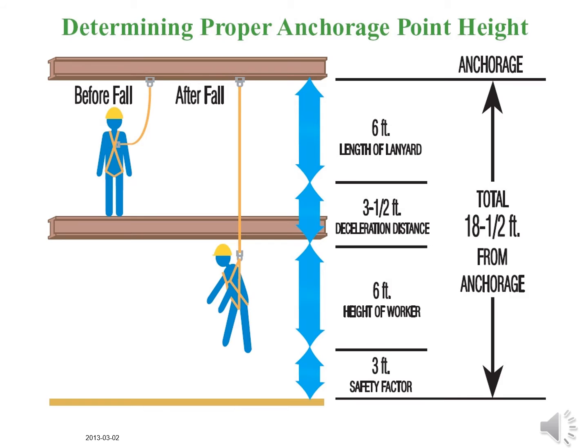Pay attention to the lateral distance from the tie-off. It's not unusual to see a worker using a retractable lanyard who has moved 15 or 20 feet away from the anchorage point. Should he fall, all of that extra cable will factor into the distance, and may even create a pendulum effect in which he swings back and forth. That's not necessarily a problem if he's in an open area, but if machinery or structural components are nearby, he could expose himself to serious harm.